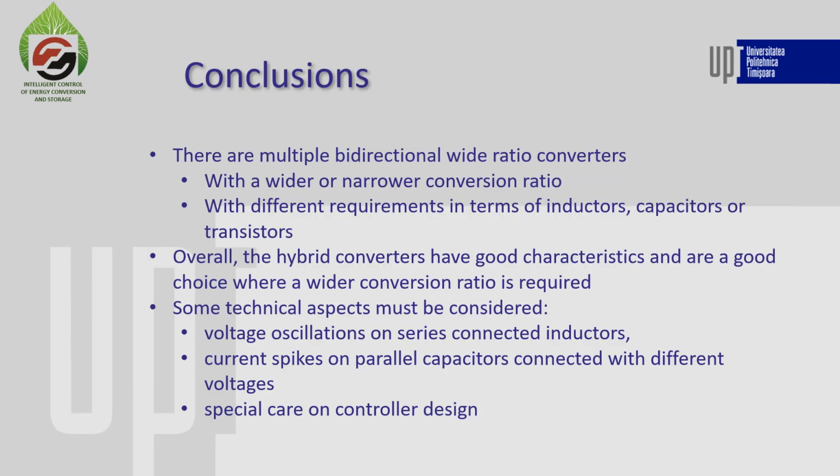So, in conclusion, we see that there are multiple bidirectional wide ratio converters available, each with a wider or narrower conversion ratio, and each having different requirements in terms of inductors, capacitors or transistors. But overall, the hybrid converters have good characteristics and are a good choice where wide ratio converters are required.